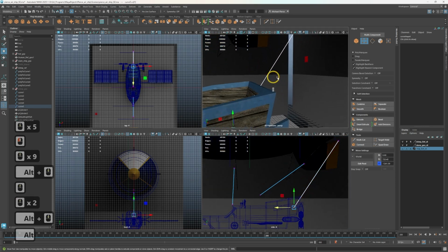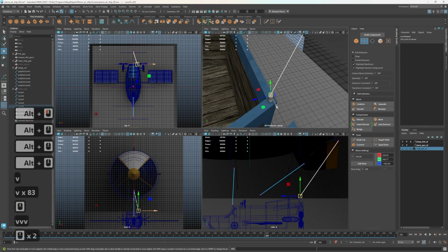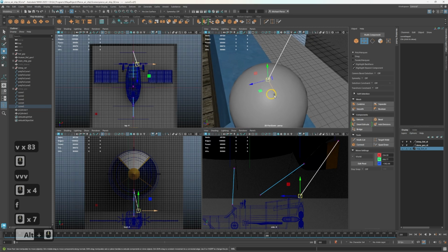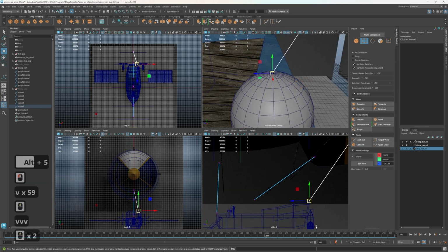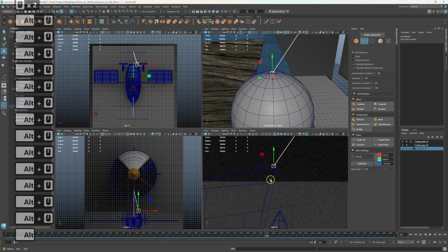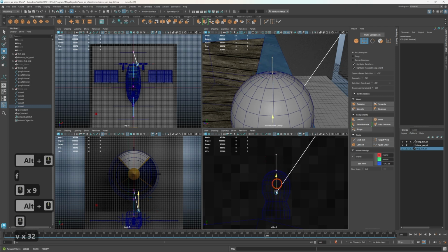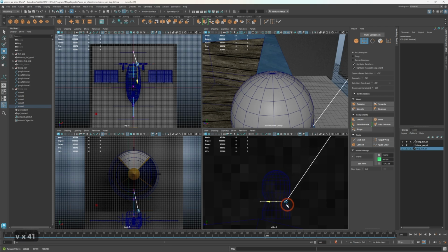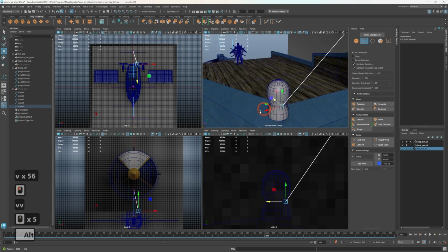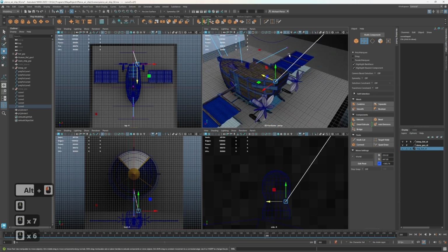Right now, for this guy, I'm going to hold V, click on the circle to make sure I bring it basically close to. If I hit Alt 5, I'm going to snap that here. Hit F in this part, zoom out, and then I could also hold V because I know I want to bring it basically around here, right? Technically, I would snap it to the outer side, so I'd hold V, snap it like this. That way, it looks like it would be coming in on the angle, and I'd have another one going around. So it looked like we tied it off, right?